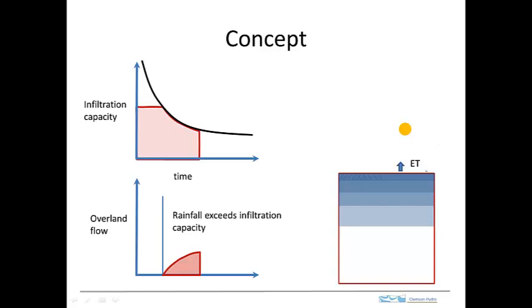So at the ground surface, we're removing water, and down here at the wetting front, it continues to move down. And so the question would be, will this water end up as recharge? Because we have these two competing effects. The ET is causing water to move upwards and go out of the subsurface hydrologic system at any rate, and gravity is causing water to move downwards. The rate at which it moves downwards will slow with time, however, if we don't replenish it.